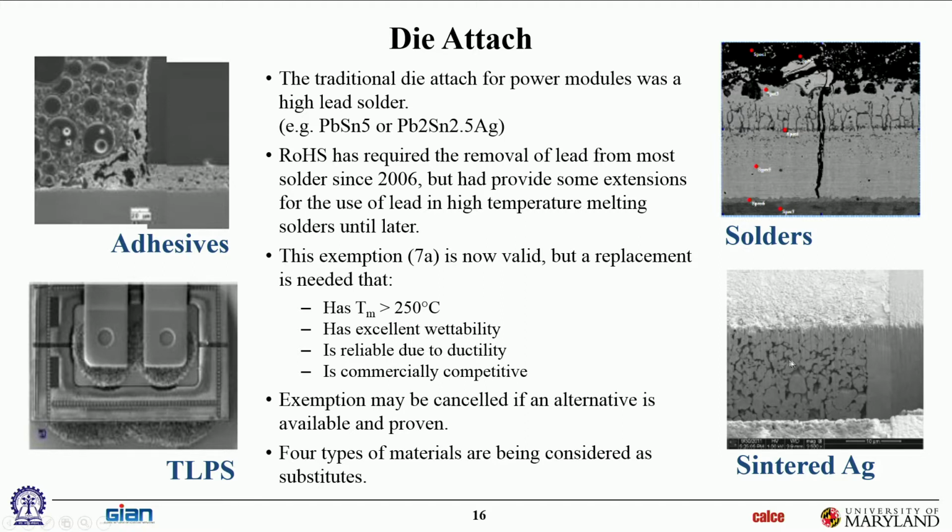There are some issues with it, but it's excellent for thermomechanical cycling. Any high strain rate loading, it's a problem. But for thermomechanical loading, just temperature cycling, it's a very robust material. It doesn't creep as much as solder because it's far away from its melt temperature. It doesn't fatigue as easily under temperature cycling because, again, it's so far away from its melt temperature, it's creep resistant, so you don't get a lot of cyclic creep strains. So it's a promising material. It's being used more and more. Cost is a problem, so only for critical applications, not for every application.